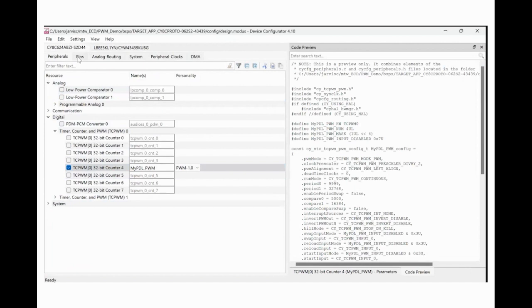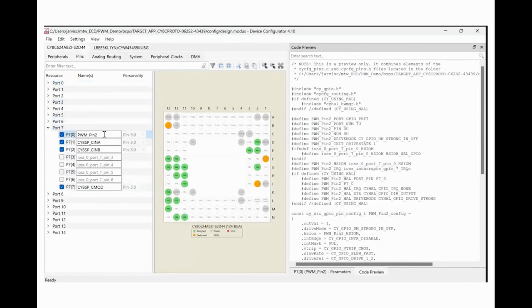And by specifying names inside of the tool, these now become software macros, software defines that if I use them in my application, I can change the underlying hardware. I can remap it to a new location. And I don't have to touch my actual application code because it's using these macro defined terms. And so this kind of feeds into the last aspect that I want to talk about, with the concept of a board support package.